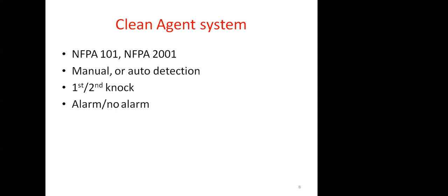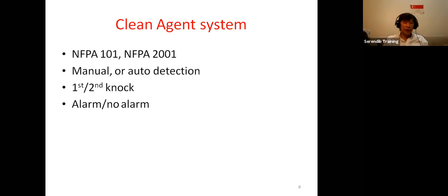Okay, thank you. The only difference is it doesn't activate the building evacuation. But if you want to program the fire alarm evacuation in the manner that you think makes sense, nobody is stopping you. It's just that it may be unnecessarily disruptive to building occupancy. But if you want to raise it to the client, to the owner, as your opinion, maybe you say, you know what, this is still a fire. The fan is on fire, overheating, a small fire in the AHU. I think we should evacuate the building. If the owner agrees, you can program it in the way that you think meets the fire objective of that particular fire system.